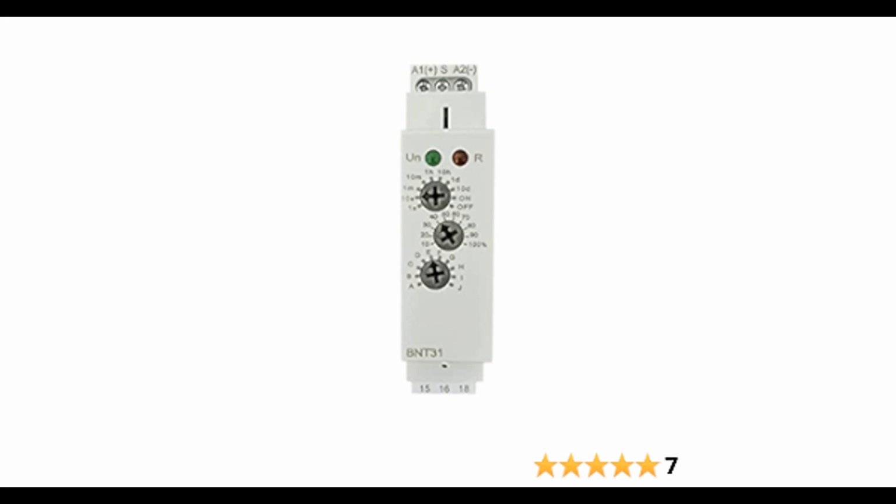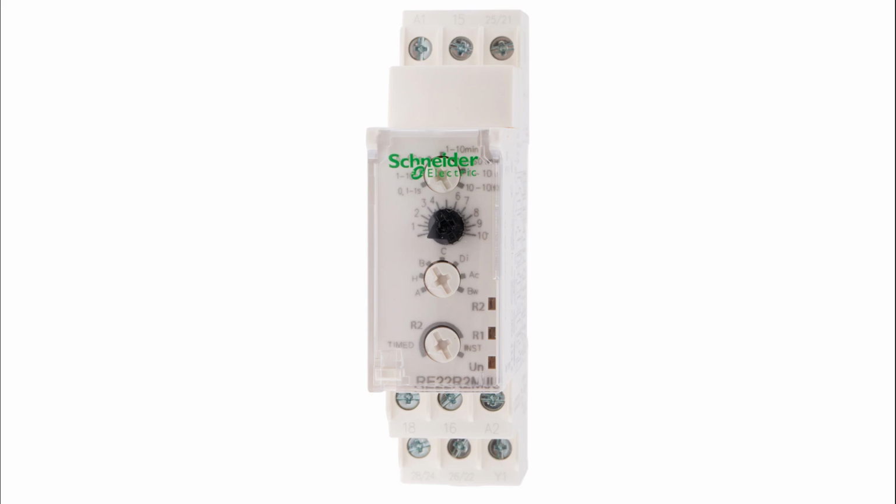High voltage and current handling. Electromechanical relays are often capable of handling higher voltages and currents compared to solid-state relays, making them suitable for high-power applications. Contact arcing. Electromechanical relays can suffer from contact arcing, especially when switching high currents or inductive loads, which can lead to contact wear and degradation over time.